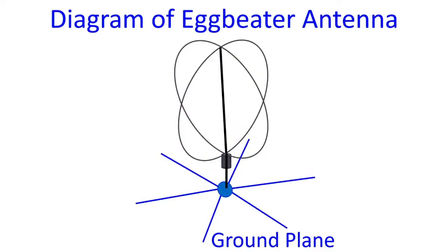Often amateur radio satellite builders use circularly polarized antennas on them. A popular form of omnidirectional antenna for a base station is known as egg beater antenna because the shape resembles an actual egg beater used in the kitchen. Another type of antenna with circular polarization is a quadrifilar helix antenna.